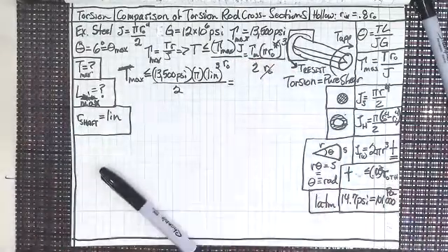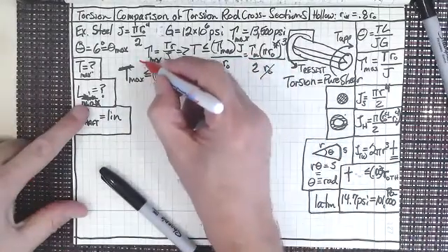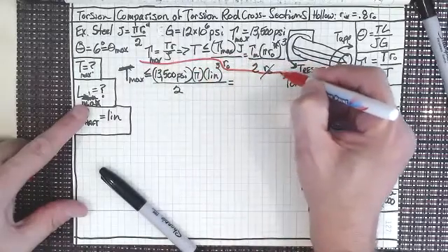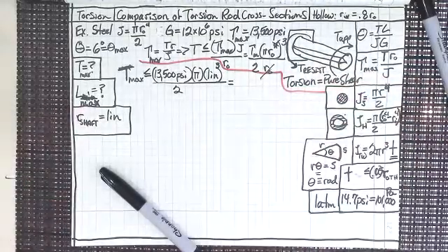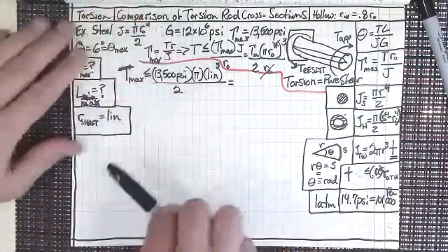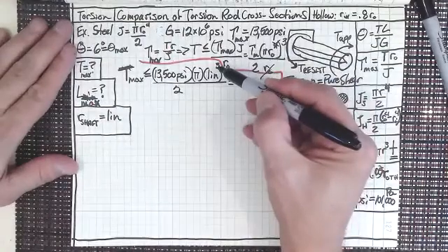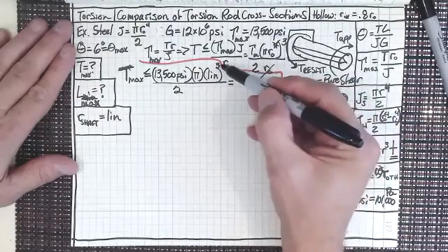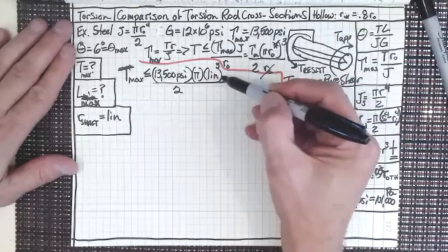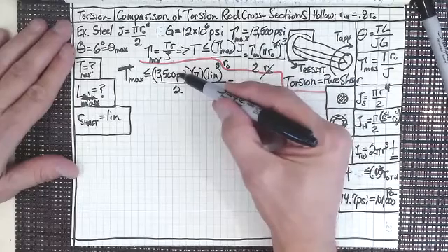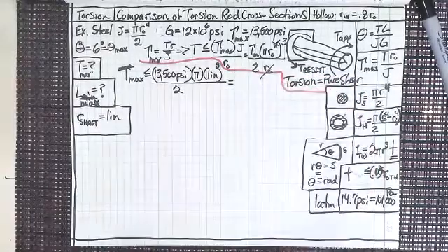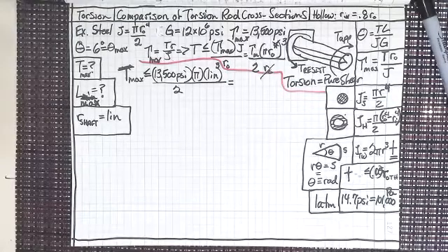Let's make sure everybody sees the way this is separated: the cube is on the 1 inch. So that's going to give us inches cubed, and psi is pounds per square inch, so we're only getting rid of 2 of those. We're going to have inch up here, and we're going to have pounds. So don't assume that when you punch all of these together your units at the end are going to work out to foot pounds, because in this case, it's not.